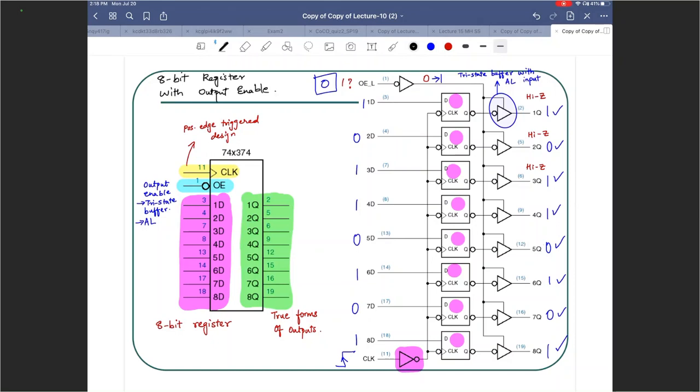So from here on out, wherever you see the term output enable being used, right away you should think of the tri-state buffer and the outputs being possibly in the high impedance state. So the outputs can be of some logic, low or high, but with the output enable terminology, they could also be in the high impedance state, which is primarily used to connect multiple outputs together, right?